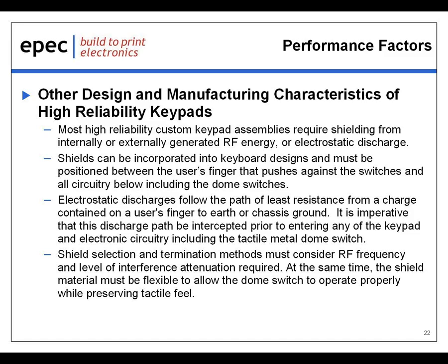If an application's circuitry is extremely sensitive to interference or the application generates a large amount of high-frequency energy internally, the shield materials have to be selected for proper performance. At the same time, the shield material still must be flexible to allow the switch to operate freely while preserving tactile feel.